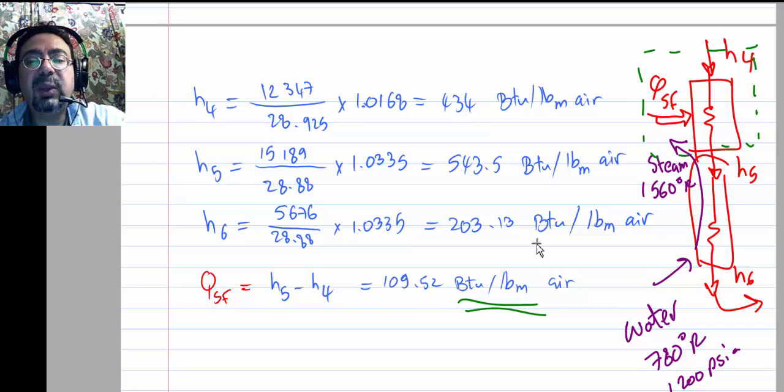So it was a long route, but the equation is very simple. If you want to know how much Q is coming over here, it's m dot delta H. And so if you wanted it per m dot, you basically say Q per pound mass is simply delta H. Done. Perfect. What's the second thing he wanted?